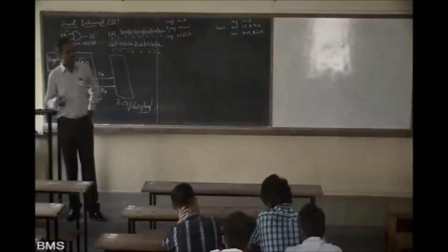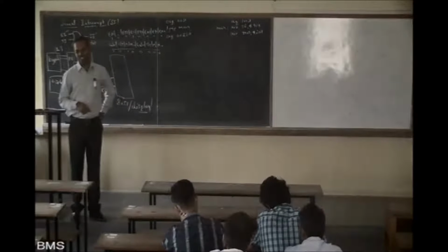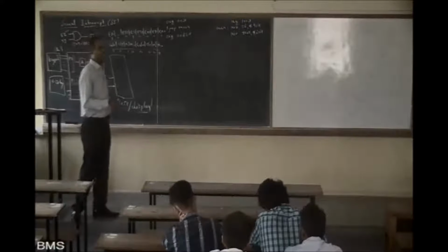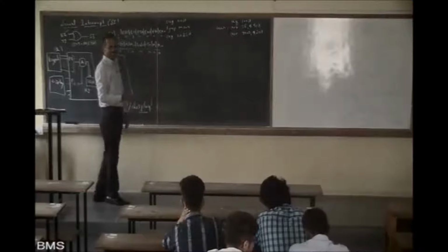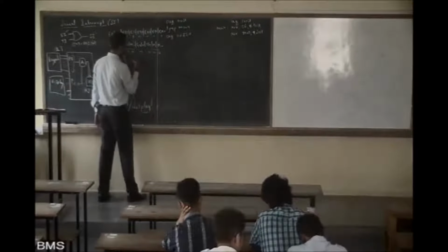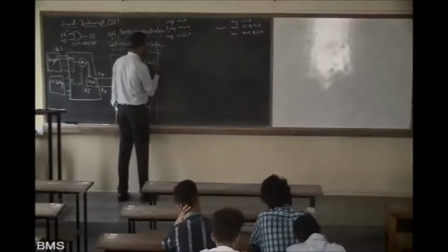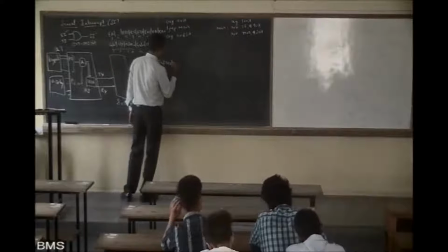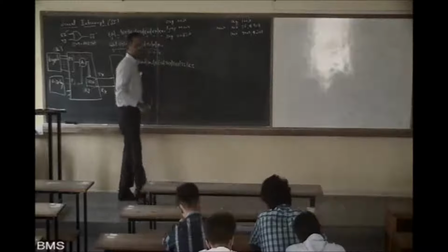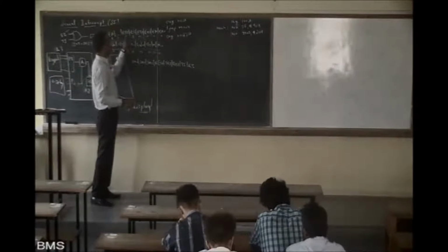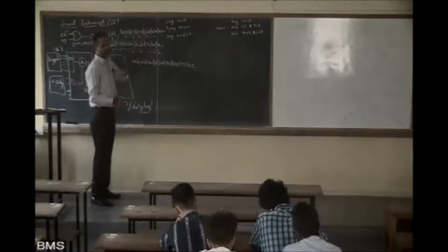There is a SCON register wherein you should set a value for serial communication. Let me know the SCON register. SM0, SM1, SM2, REN, TB8, RB8, TI and RI. This is the SCON register. This is TMOD. This is the IE register. Now, what should be the value to SCON for serial communication?